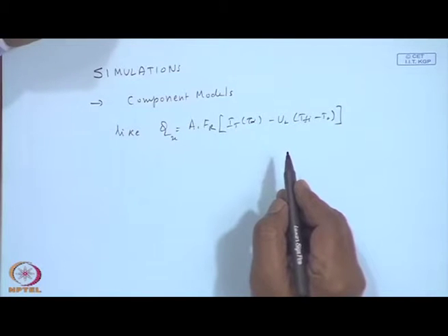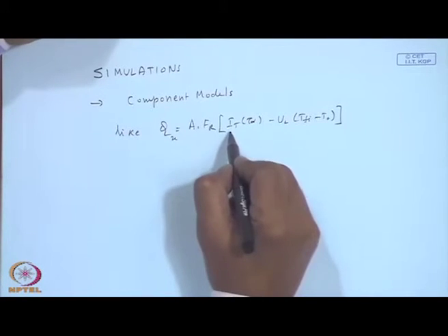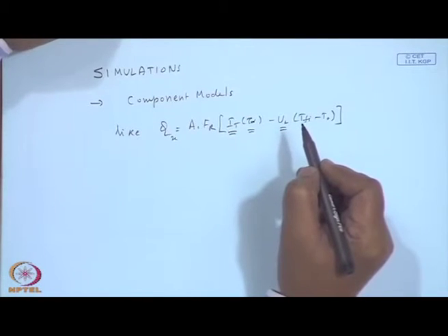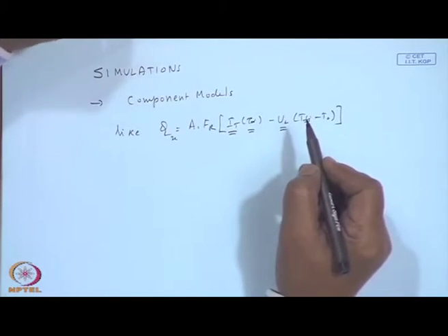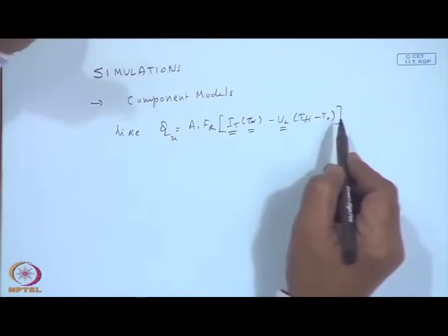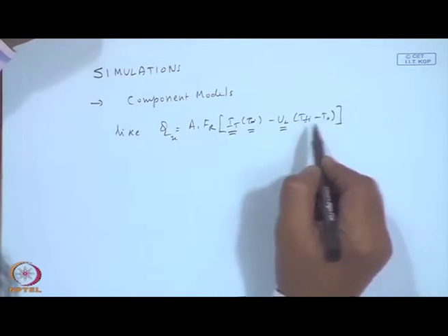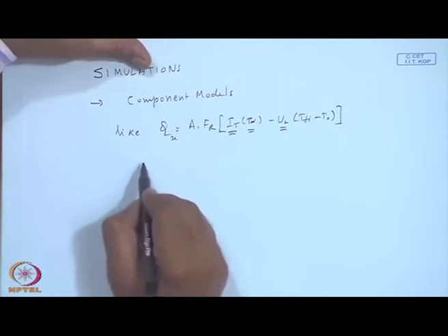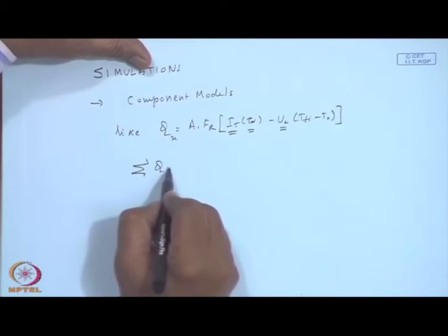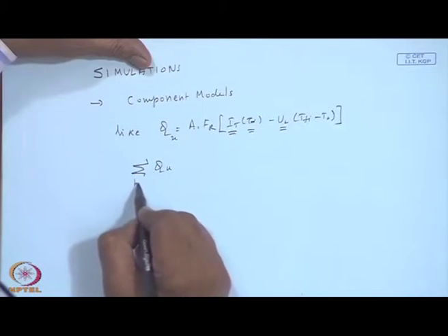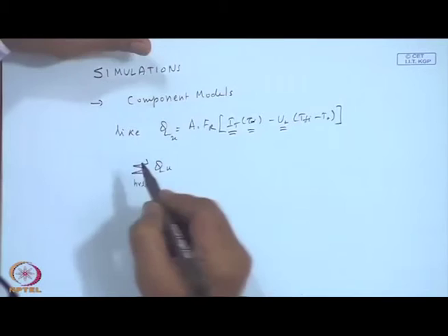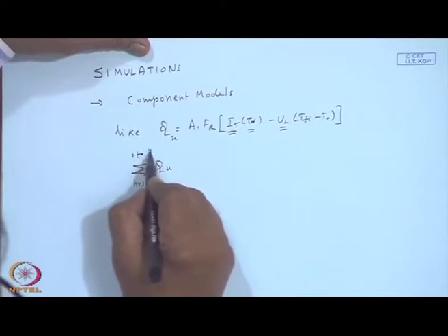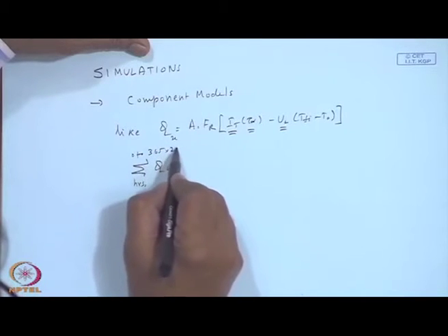I have the weather data file and process it to calculate I_T tau alpha and estimate U_L by the methods we have described for the conditions of operation, and then multiply by of course T_FI minus T_A, and I keep on adding this Q_U over the year, sum it up, Q_U hours, all hours, from 0 to maybe 365 into 24.